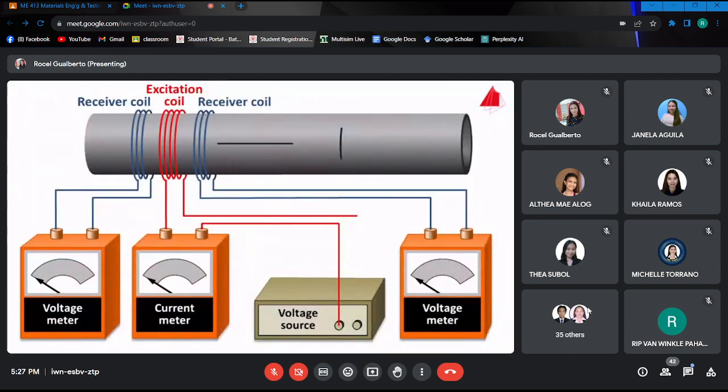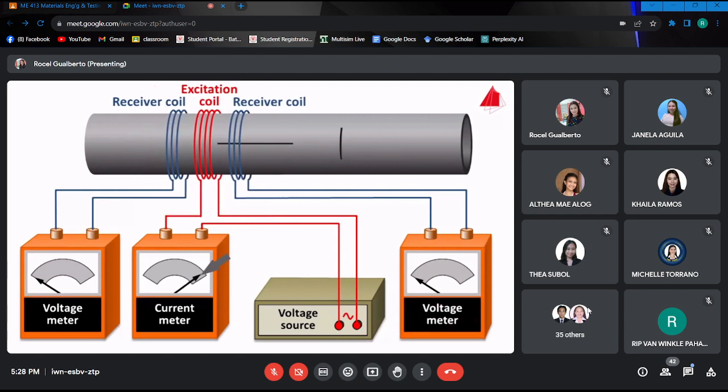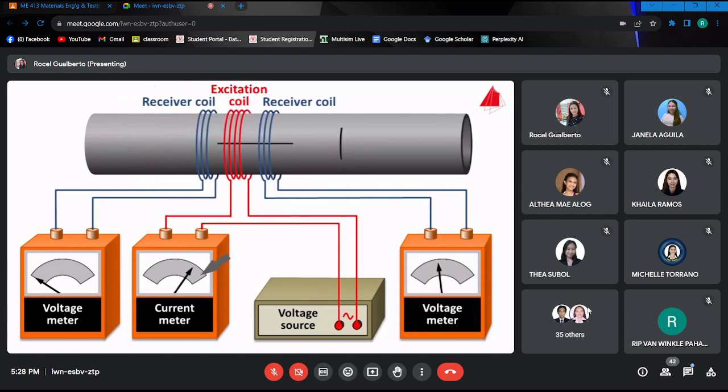The animation once more shows the physical background. The current consumption is high in an area where the tube is intact. The reason for this is the undisturbed flow of the eddy current. Because the magnetic field of the eddy current doesn't flow through any of the 2 receiver coils, we measure virtually no voltage on them.